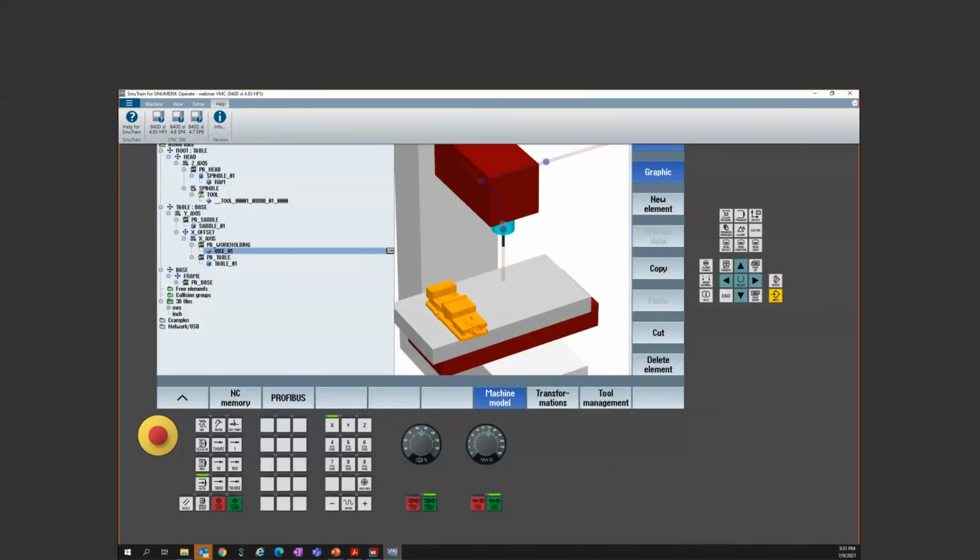All right. Switching to millimeter, will everything convert okay? Yes, it absolutely will. Once you build it, then you can bounce it back and forth. Now, I will caveat that: I have found in some of the more complex 5-axis systems, in older versions of SinuTrain, I haven't tested in 4.93 yet, that it may calculate the swivels and the TRAORI funky if I'm powering up in a different unit of measure than the machine was built in. But that is also machines that I built completely out of STL files. So I think it's a funky thing with the conversion of the STLs.